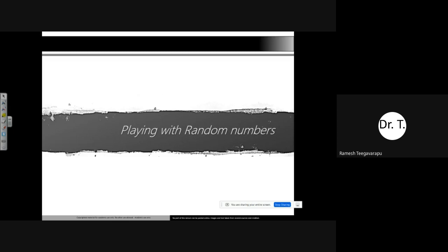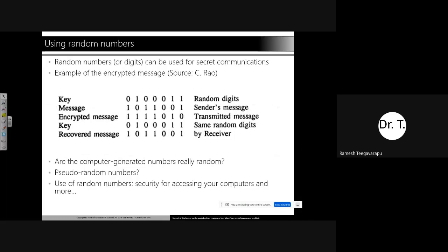Typically, because you're trying to change your data sets, we have to work with some random numbers. We can do a simple random sampling of your data set, or we can do a Monte Carlo sampling, which is the same as simple random sampling. And then we also have what we call Latin hypercube sampling, which you might remember from your theory, or might have already implemented in your research.